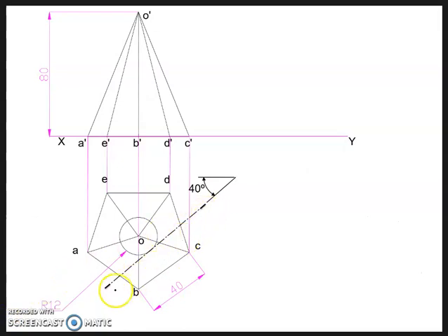Okay. Mark all the points on the section plane which intersect with the slant edges as well as the base edge. Okay. So you should get these 4 points: 1, 2, 3 and 4. Right. So you get 4 points of intersection. So this is your section plane, and these are the points of intersection of the section plane with the base edges and the slant edges of the pyramid, and it is constructed in the front.